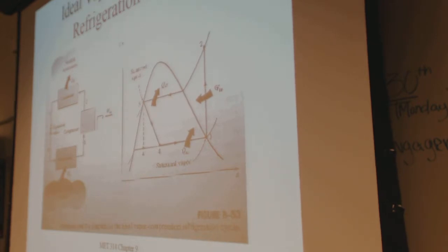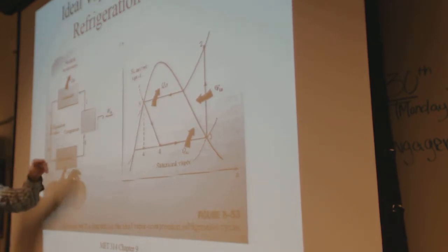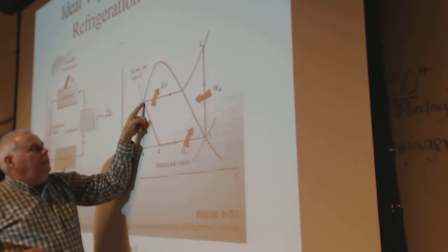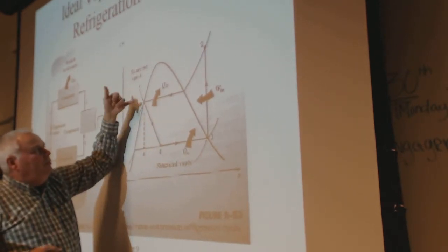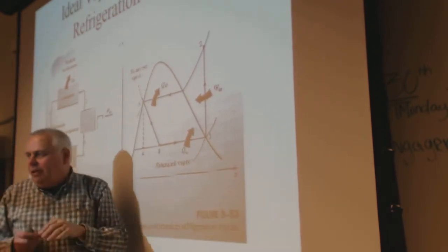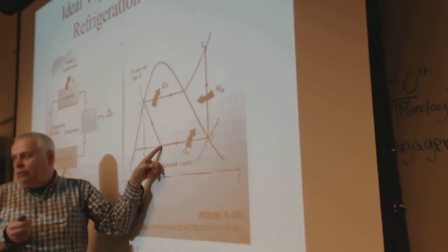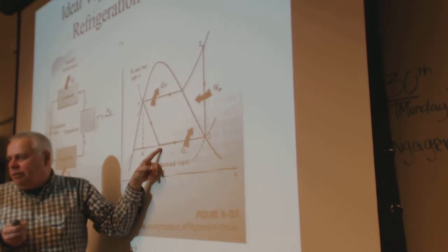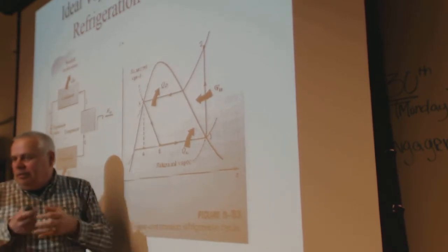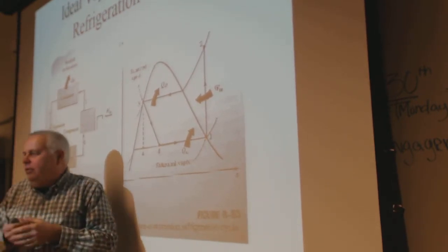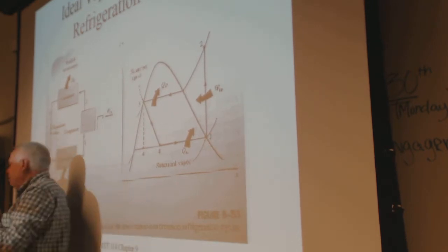And what's the same is, it goes down to saturated liquid, and then we evaporate it. It's going to have the same enthalpy, not same entropy, same amount of energy at 3 as at 4. And that's actually pretty real. Same energy. We didn't put any work into it. We insulate it in that process.